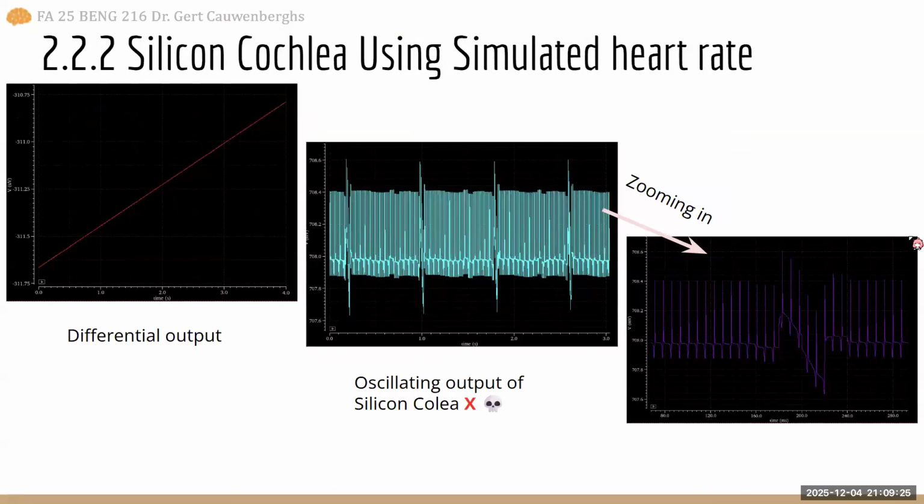And then here are some of the other tests with the actual natural heart frequency, where we're seeing that same sort of voltage creep coming from somewhere within the circuit. And of course, that basically just leads to a large DC offset. If we can't select for that output, then we have to select for one side of the differential outputs. But then it comes with such a large DC offset that it basically just drives the pulse generator at the same frequency no matter what. And none of that signal actually matters because it's dominated by the DC offset.